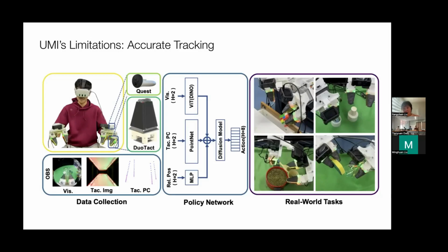So basically the naive version of RGB SLAM will not work for a lot of cases. Also for bimanual, you're consistently seeing the other gripper moving. So for moving things, this RGB SLAM will also fail to locate where your gripper is.